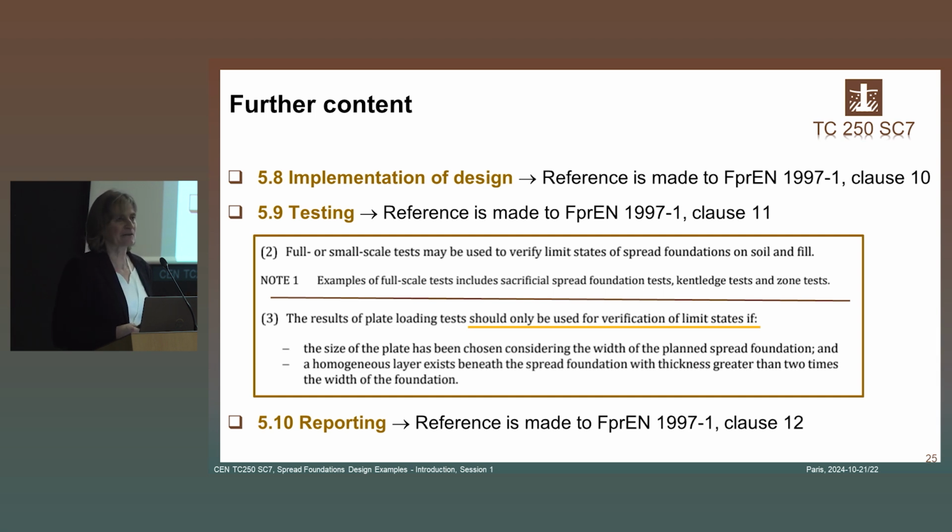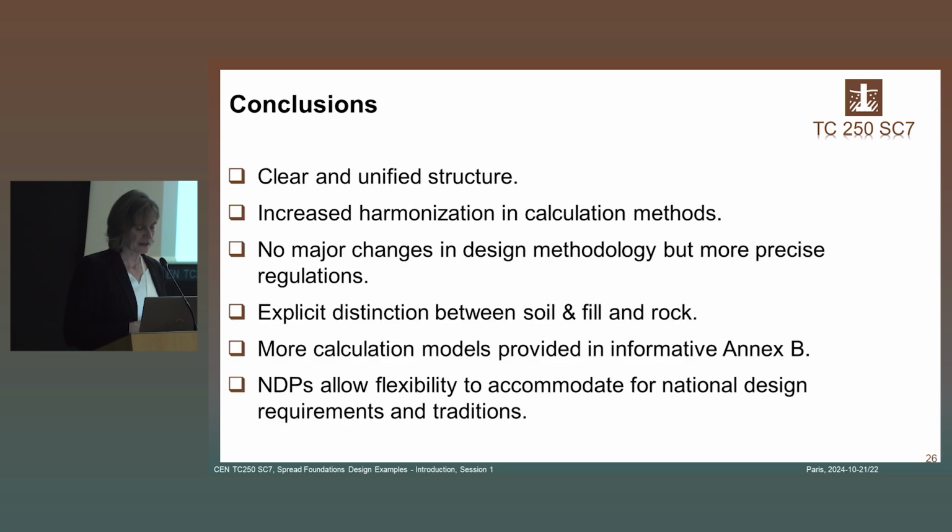Because usually the size of the plate is small compared to the size of your footing, so only a reduced zone of influence is analyzed by the plate load test. So this is what you have to keep in mind. Otherwise, you should be very careful in using this type of test for the design of spread foundations.